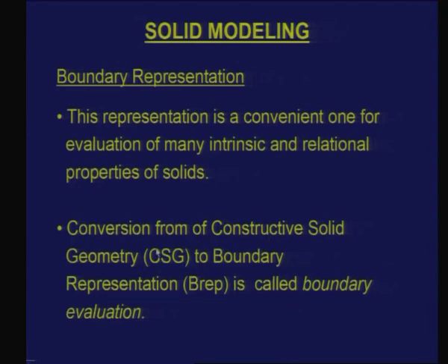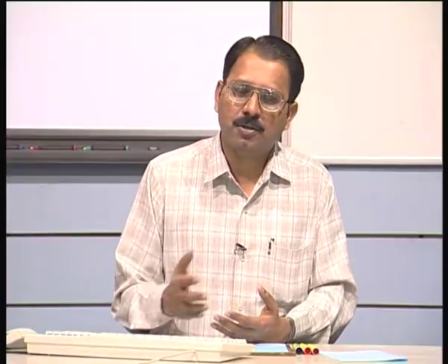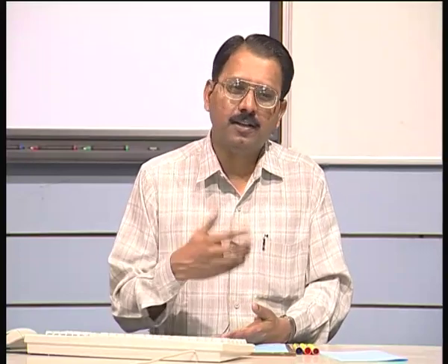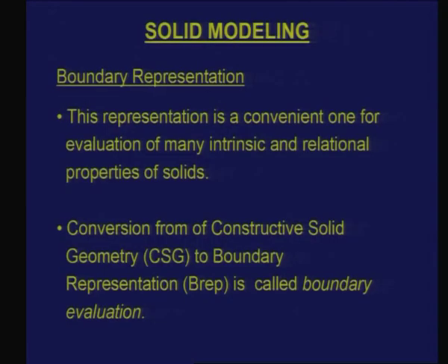As I said, if I want to build an object, constructive solid geometry may be a convenient method, but for certain applications boundary representation may be better. So I should also have a method of converting from one to another. I build using constructive solid geometry and convert into a boundary representation. This method is called boundary evaluation. Boundary evaluation is a very common feature in most CAD/CAM applications.